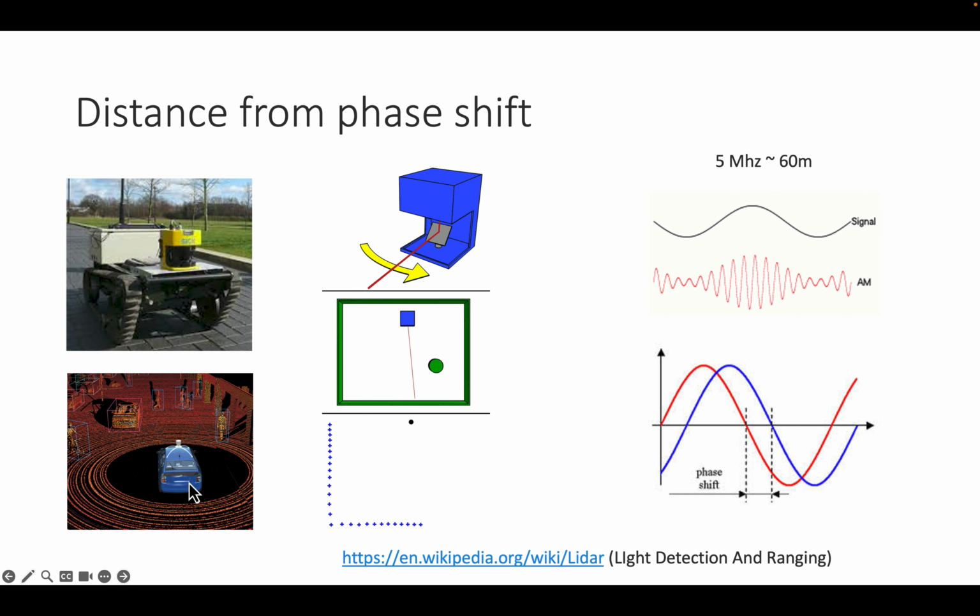Now, Tesla is not using these kinds of sensors, and if you read the news, there is sometimes public discourse on whether you should be able to do autonomous driving using cameras alone, like Tesla believes, or whether you have to mount these laser scanners. There are pros and cons. The laser scanners are, of course, expensive. They also don't work very well in rain. Yet we like to have more data than not.